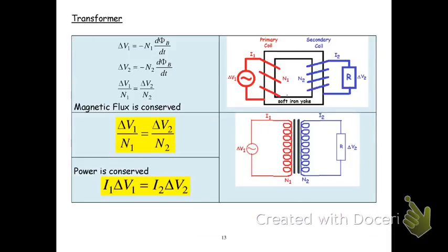Final little bit. I'm just going to mention this so I can finish off the tape. On a different tack, the reason why we like AC so much is because we can use transformers, mutual inductance. The key equation for mutual inductance is that the ratio of the turns is equal to the ratio of the voltages.